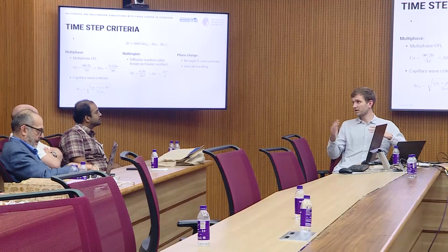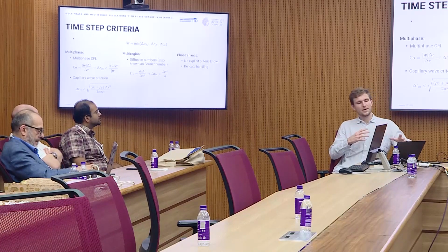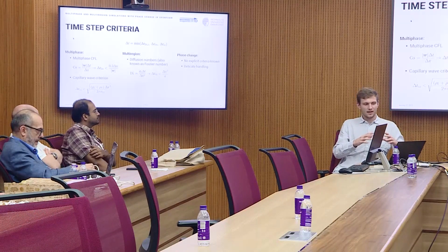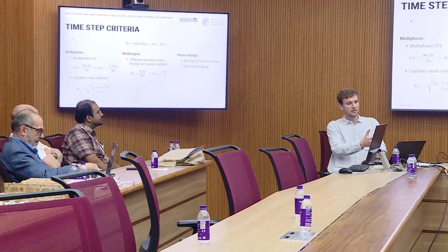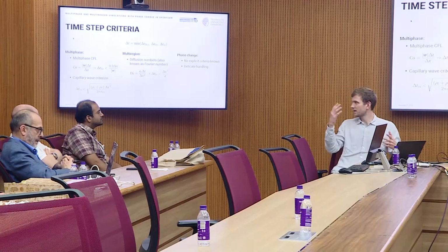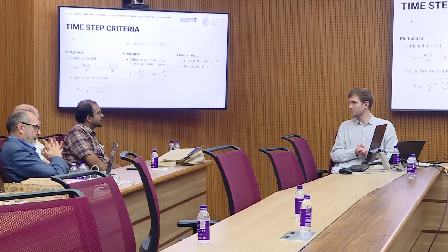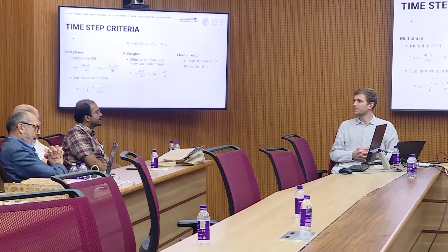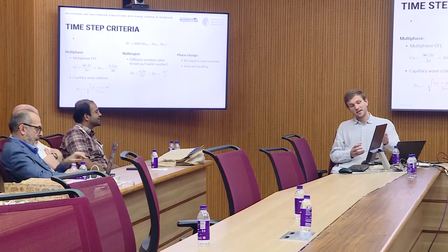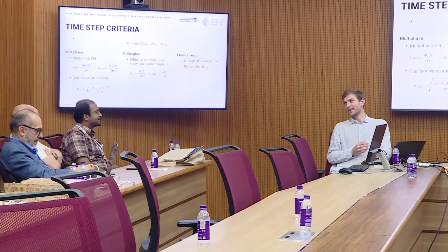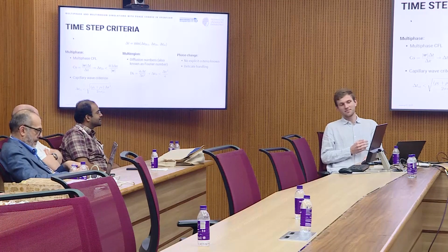In OpenFOAM, we use implicit time discretization. So it's less a strict limit, but a recommendation. I have experience: I can sometimes choose much larger values, sometimes not. In theory, implicit is unconditionally stable, but we never run the risk of taking a very large CFL number, by the way.